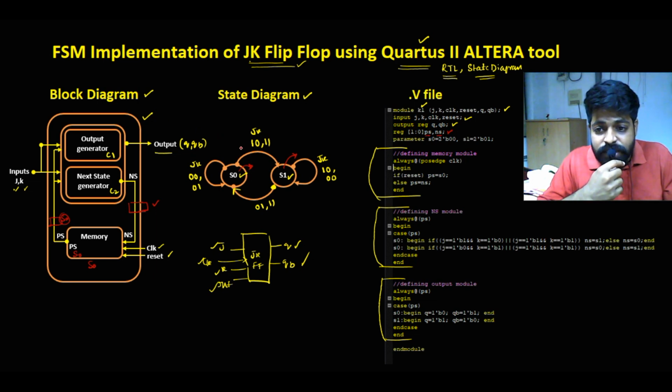Let us suppose S0 is represented with 1 bit 0 and S1 with 1 bit 1, like tail is assigned to one and head to the other, because I have two states. Wherever we have 0, that is the representation of S0, and wherever we have 1, that is S1. But the problem with assigning logic 1 and logic 0 as symbols is that we use 1s and 0s multiple times, so the tool gets confused and cannot generate a state diagram view for the given assignment.